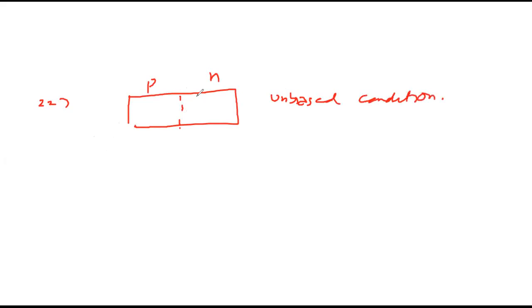When no voltage is applied, the negative electrons of the N side diffuse with the positive holes on the P side. So P becomes negative and N becomes positive. There exists an electric field in the space. So they're telling if no voltage is applied across PN junction, there will be an electric field pointing from N side to P side across the junction. Correct? A is correct.